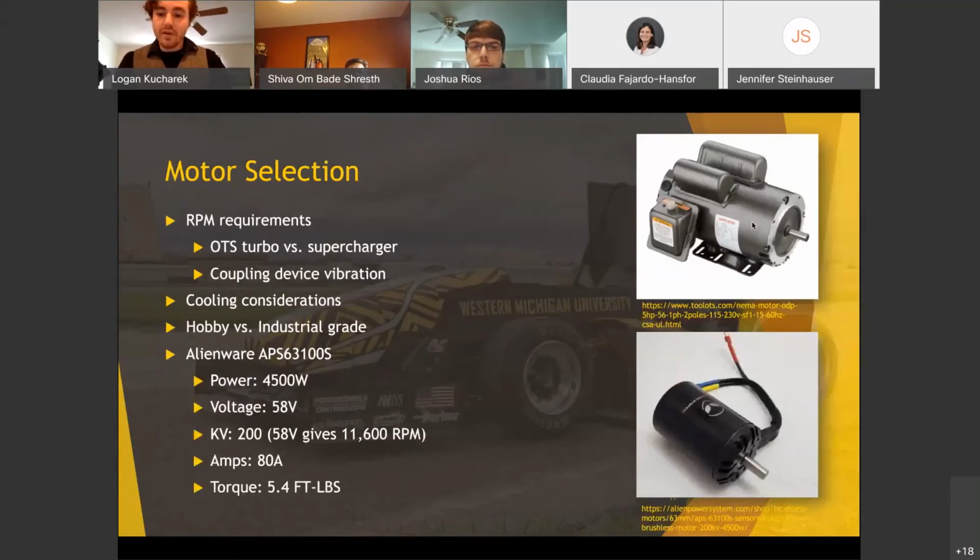So utilizing the original design concept presents many issues with motor failure too. Electric motors cannot sustain speeds of 200,000 RPM for any extended period of time. A very extensive liquid cooling system would need to be implemented to prevent the bearings from melting, and if it faltered for even seconds, motor failure would be imminent. Furthermore, any deviations from perfection in construction of the coupling device would instantly surface at 200,000 RPM, and the motor could potentially vibrate or melt itself to destruction.